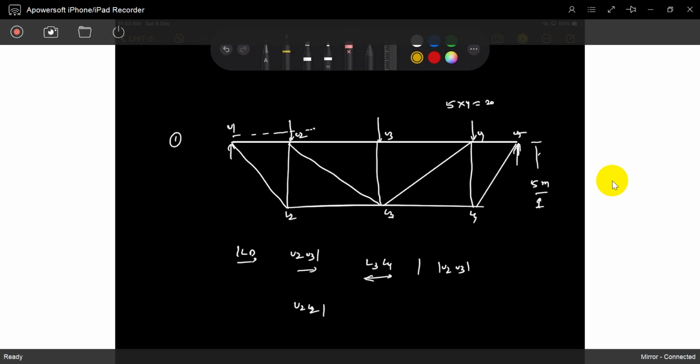So this is the vertical member, this is the upper chord, this is the diagonal member, and this is the lower chord. Can you develop it? Try it. Very simple. Just do what we discussed in the last two classes. You can easily develop it just by the method of sections. Cut it, cut it.